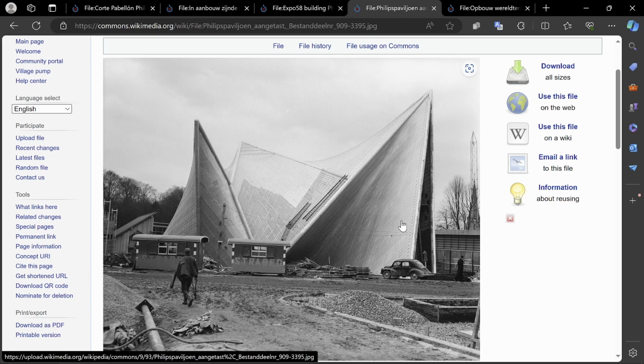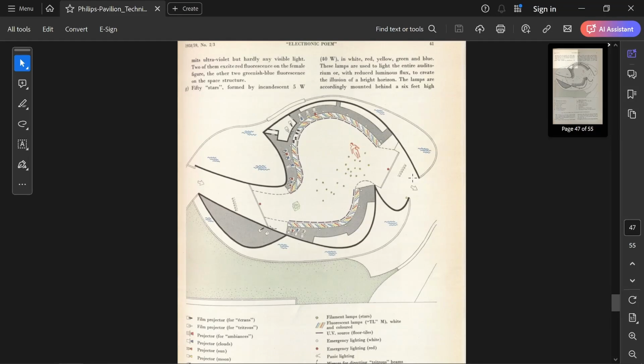And in real life, when it comes to the geometry or the construction of this, they needed to simplify the geometry to make it more constructible. If you read the history of this, it was actually more complex than this. But there was a give and take with the structural engineers on how to make this simpler, and that's why they switched to a hyperbolic paraboloid, where all of these tension cables that you see here are literally straight.